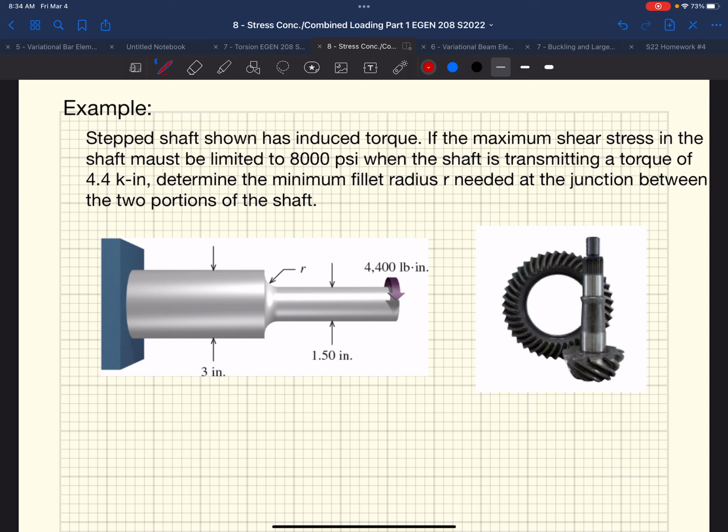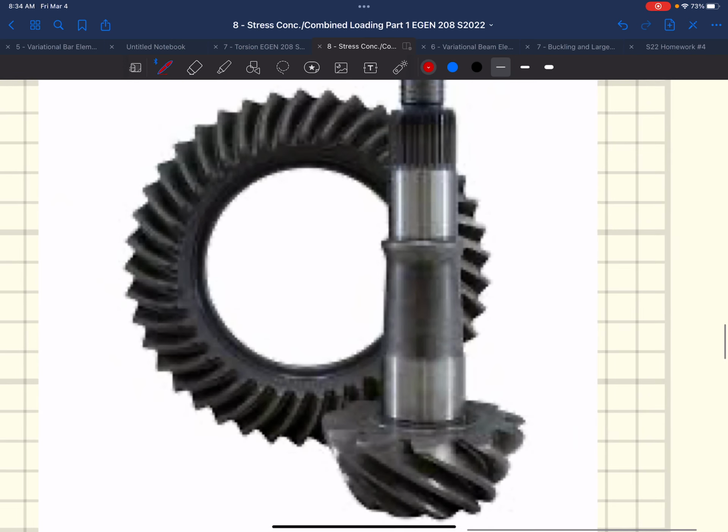There's a big void between our rear axle, or our rear tires. We need to take that rotation of our tires, and we have a drive shaft that's running perpendicular to that. So we end up running a pinion gear on this ring gear to take rotation around the ring gear and rotate it the other way around our drive shaft. So this pinion gear drives our drive shaft, or our drive shaft drives the pinion gear, and then we're driving our vehicle's tires.